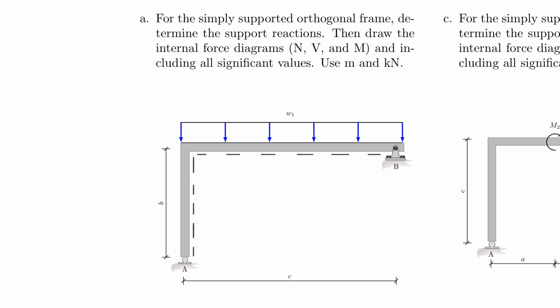But you need to communicate where the bending moment is positive and where the bending moment is negative, so that later on engineers actually know, for example, where to put the reinforcement steel and so on. You will learn this in later classes, but it is very important that you identify where the positive and where the negative direction is. So I suggest that for this frame, you just put it on the inside, and then I think everything else is as before.